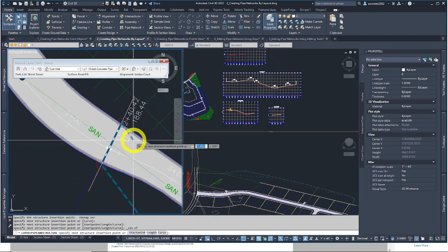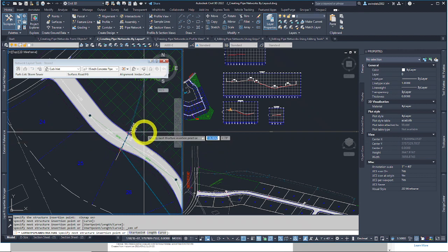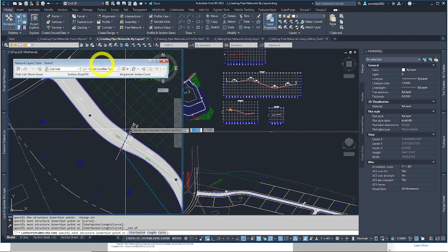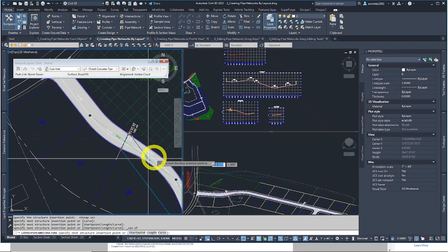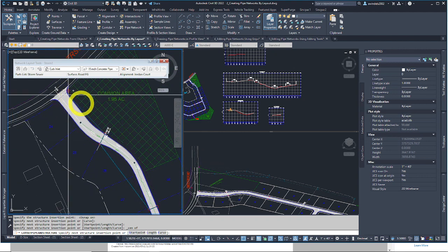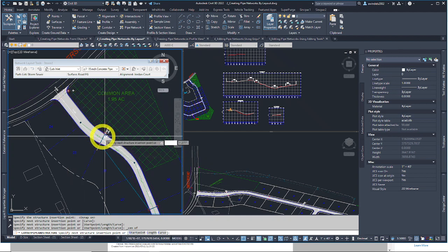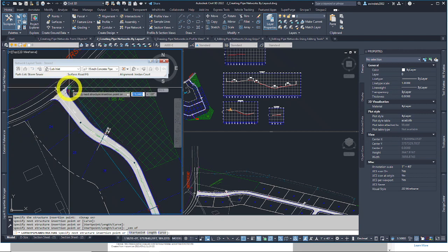And I've inserted several structures and pipes now. I did have these nice spots to help me locate them, which is handy with the book to have those. We would not always have that in a real world drawing. So along the lines, I should have changed my pipe diameter up before I picked this fourth one, but that's fine. Just for instructional purposes, we get the gist of it. But before I go to the next one, let me do at least that. So this should have been an 18-inch pipe in here, but I did not do that step. And we'll continue on to the northwest.